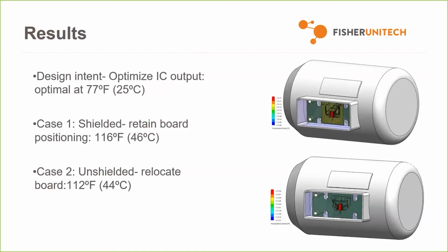So essentially, we're not going to want to have that shielding act as that sink towards the IC, which basically means for the unshielded case, we're going to have to relocate that board to a less noisy area and basically get it away from those supply voltages from our panel.